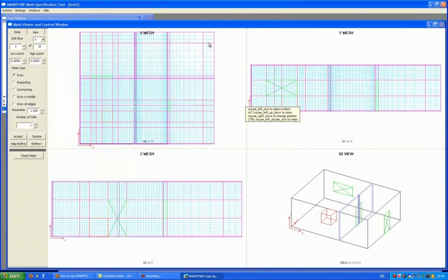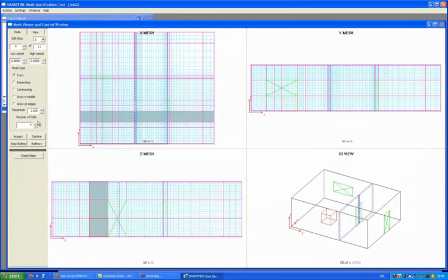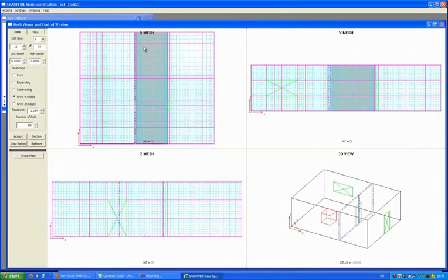At this stage, the meshing system becomes a manual meshing system, and if you now want to change any of the cell numbers in any of the region blocks, you can do so by selecting the block and changing the number of cells. If any particular region does not seem to have a very good quality mesh, you can also change the meshing type. So for example, this block here has a growing in the middle type of mesh between the lower Z and the higher Z region limits. So in this case, it may be better to apply an even mesh and reduce the mesh budget slightly.